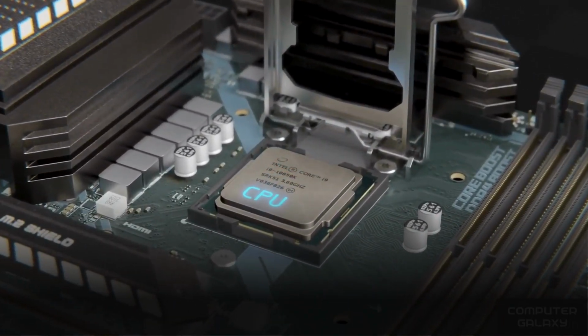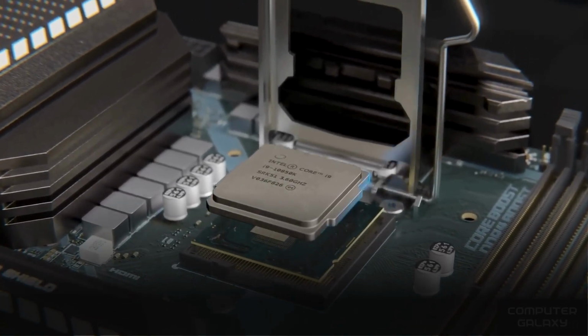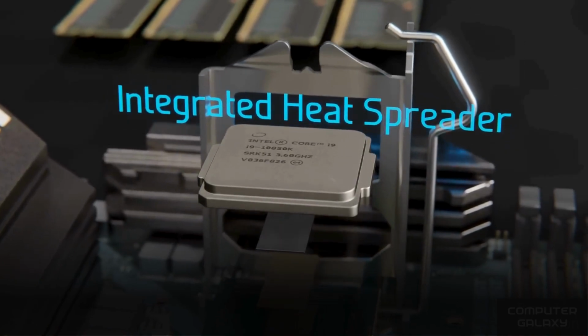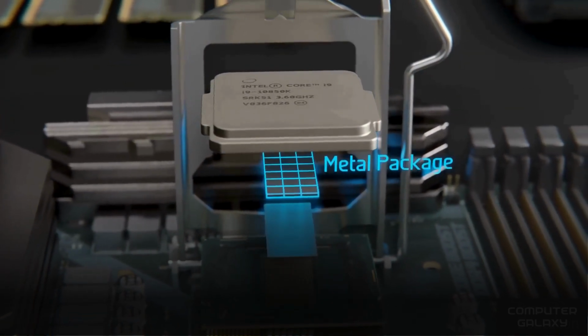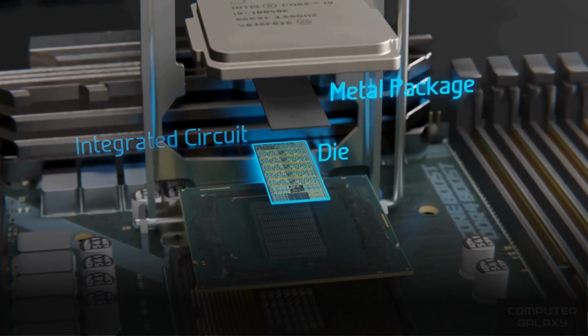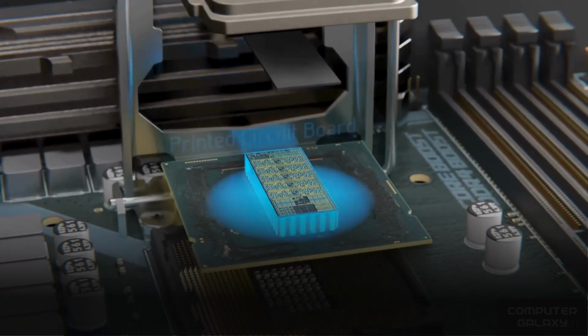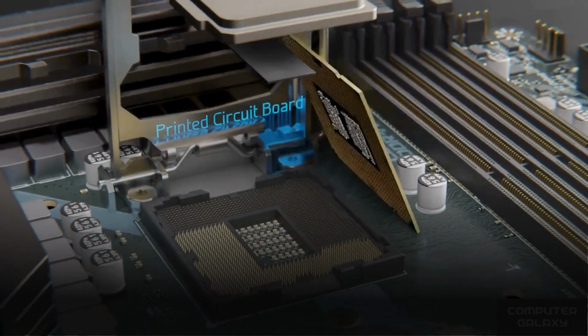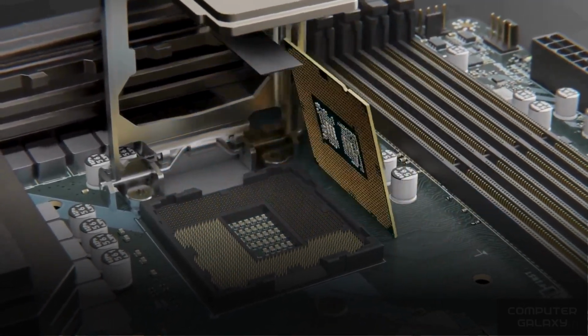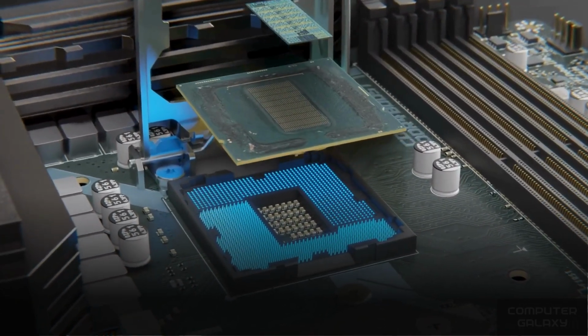CPU, which is the brain of the computer. On top, we have the cover, called an integrated heat spreader, and inside is a smaller metal package that holds the integrated circuit, which is technically called a die. This die is mounted on a printed circuit board that distributes the 1200 connection points to landing pads that interface with the land grid array on the motherboard.